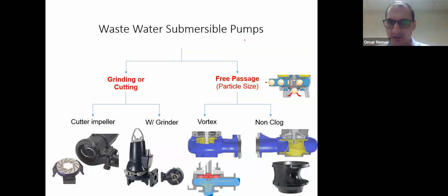It's completely different. The first type, or first group, of submersible pumps is the free passage, which follows the free passage principle. What do we mean by the free passage? We mean that these kinds of submersible pumps take the water with the dirt in it, with the solids, with all impurities, and they pump it as it is.